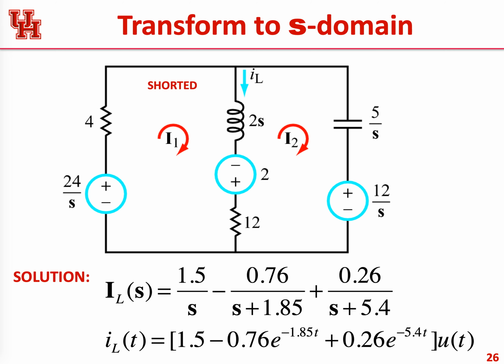Now, when we short circuit the resistor, this 8 ohm guy suddenly goes away, right? So let's see if we can rewrite this circuit without the 8 ohm resistor. So the 8 ohm resistor is short circuited, it goes away, but the 4 ohm resistor is still there, right? The battery is still there, right? It's 24 volts, so in the Laplace domain it becomes 24 divided by S. And this resistor goes away because of the switch that was flipped, and this inductor was 2 Henry, so it becomes 2S in the Laplace domain.